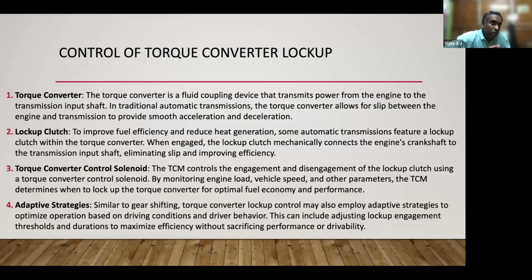You will have a fluid-based coupling. Okay? Instead of having a spring-based, usually our clutches are coming with springs. Right here, it is fluid coupling. Basically, it is hydraulic fluid pumped inside, and because of the fluid pumping inside, there is a sufficient pressure between the plates, and it will transmit the power from the engine to the shaft. This is fluid clutch, and the torque converters are used or associated with fluid coupling.